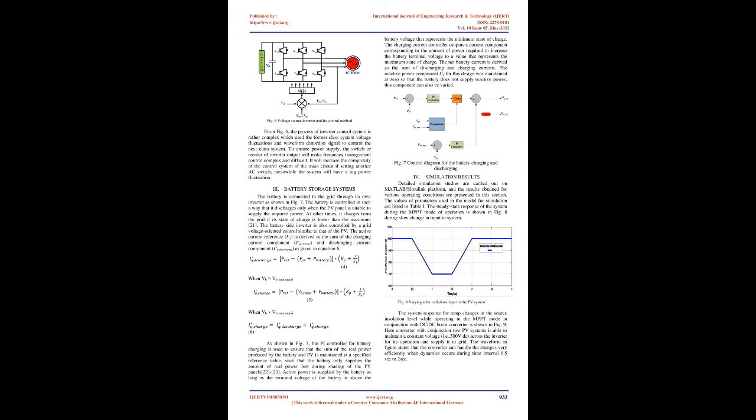Grid-connected inverter. A grid-connected PV generation system is mainly composed of the PV array, the inverter device with the function of maximum power tracking, and the control system. The inverter device with the function of maximum power point tracking can invert the electric power into sinusoidal current and connect to the grid.